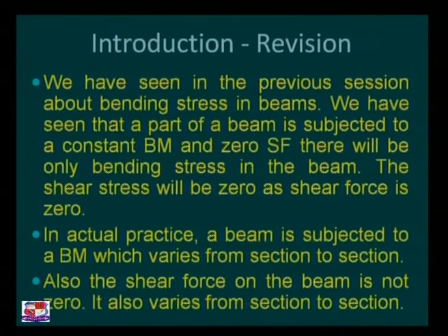In the case of bending stress in beams, we have considered purely the bending moment effect on the beams. In that case, a beam is subjected to a constant bending moment and zero shear force, and there will be only bending stress in the beam. The shear stress will be zero as the shear force is zero.